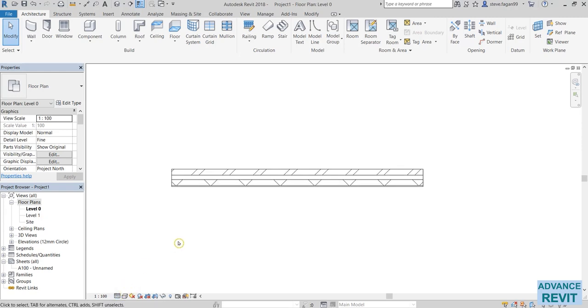Medium and fine would generally have the same detail finish, but if we were to display, for example, a door or a window which would have more detail than a wall, then you'd see the variances between the medium and fine. So the purpose of that, if I go back to our coarse level, if we were doing just typical sale plans or a planning drawing, we don't want to show the full detail level of the current wall, so we'll just use the coarse.